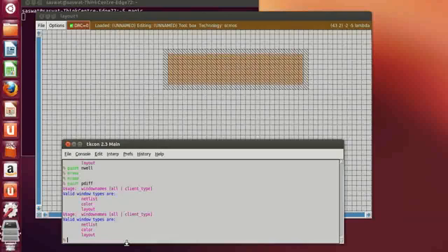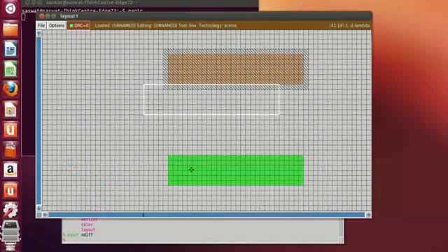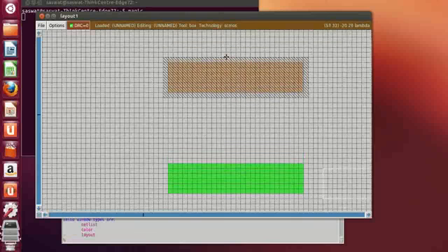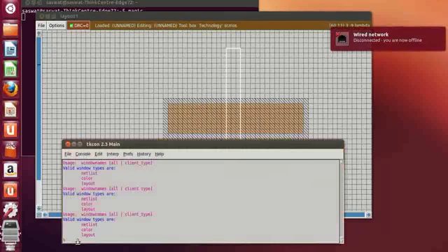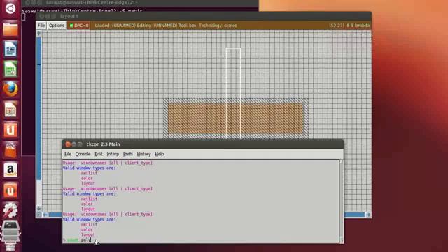In order to draw the NMOS, type paint ndiff. Now after drawing this PMOS and NMOS, we know in the transmission gate the drains of the two MOSes are shorted and the sources of the two MOSes are shorted. So before that, let's draw the poly layer just to show the gate terminal. We know here the gates are not shorted in the transmission gate. So type paint poly.